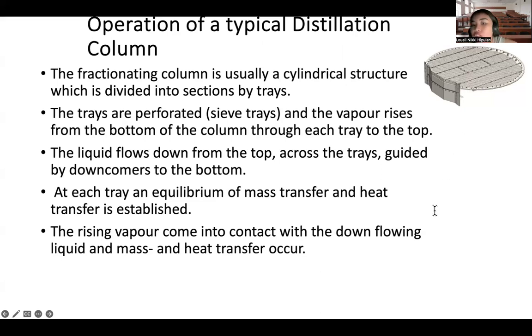And then there is mass and heat transfer. So because at each tray, an equilibrium of mass transfer is established where your components of higher volatility transfer to the vapor phase and less volatile components remain in the liquid.